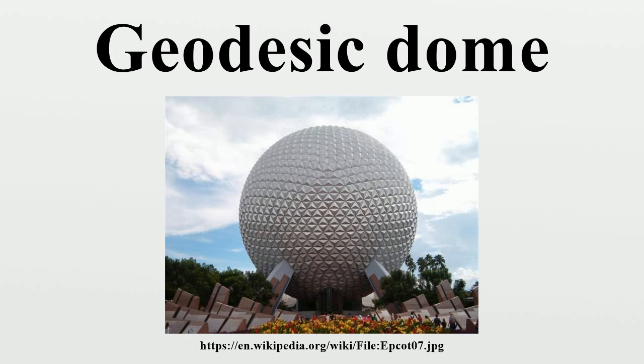For simple geodesic domes, curves follow the surface of a sphere circumscribing a regular polyhedron with triangular faces. The desired frequency of the subsequent geodesic spherical dome is the number of parts or segments into which a side of the underlying polyhedral triangle is subdivided. The frequency has historically been denoted by the Greek letter. By connecting like points along the subdivided sides, a natural triangular grid is formed on each face of the polyhedron. Each segment of the grid is then projected as a chord onto the surface of the circumscribing sphere.